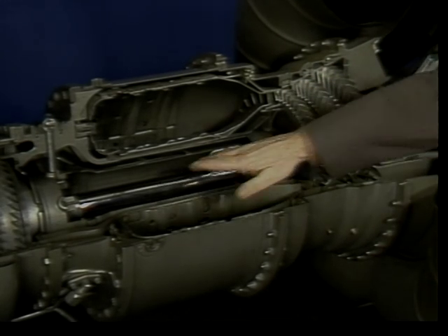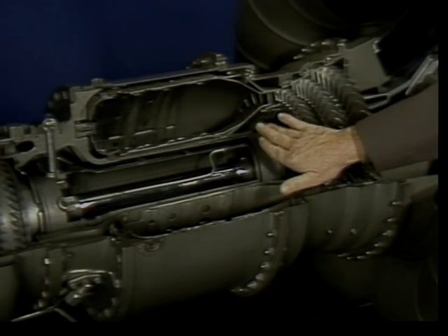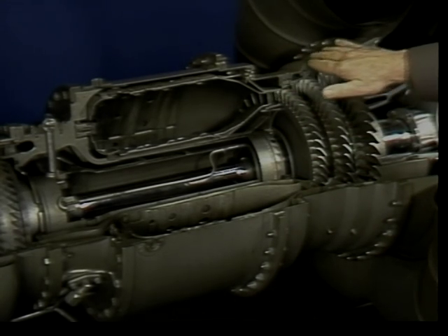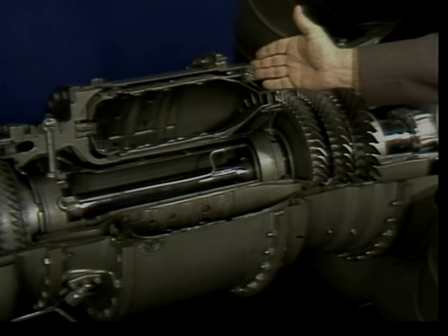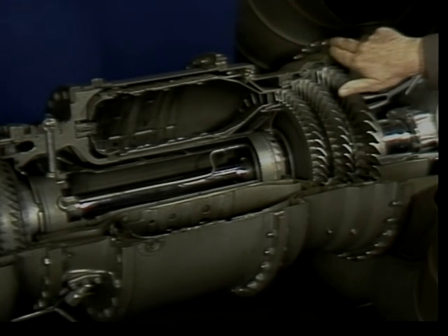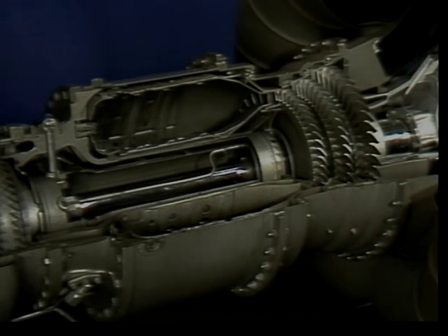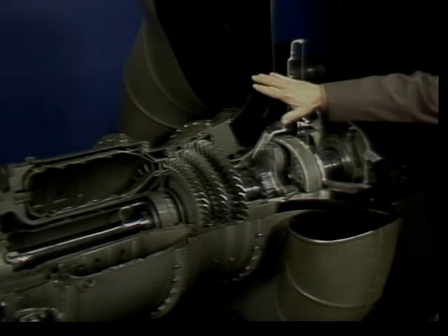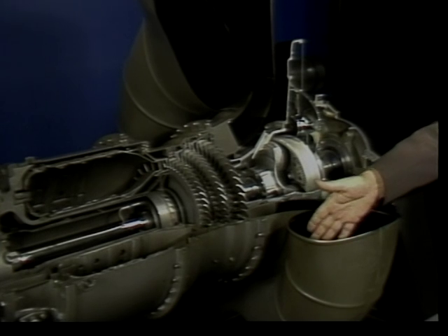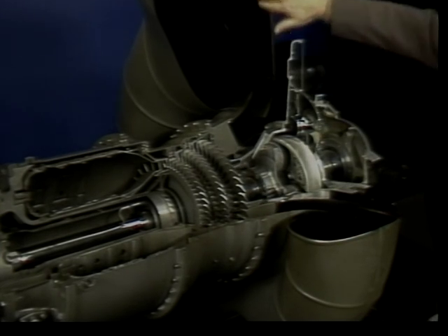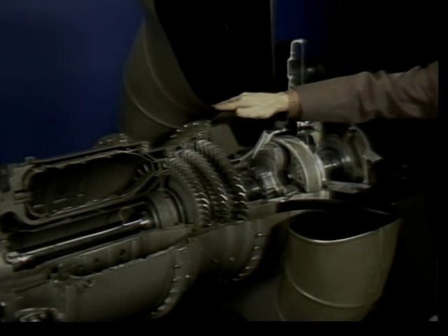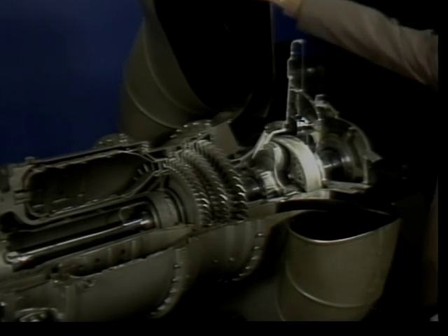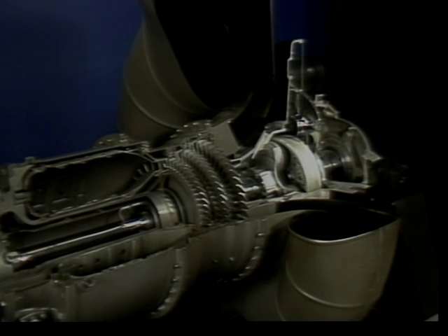The turbine shaft is supported on the aft end by a bearing. Part of the structural shell of the engine is formed by the turbine case, which is bolted between the combustor case and the exhaust diffuser. Between the turbine rotor assembly and reduction drive is the exhaust collector. The exhaust section consists of a fabricated exhaust collector and a cast exhaust diffuser whose function is to direct hot exhaust gases to atmosphere or to a heat exchanger.